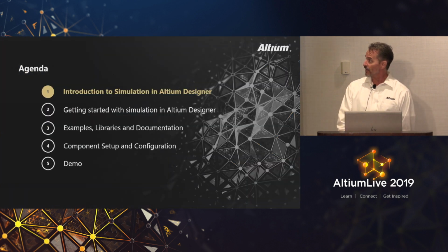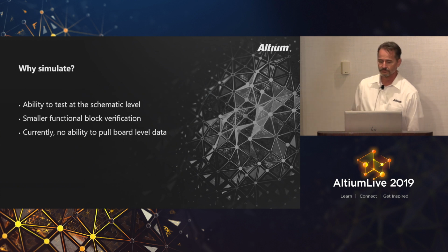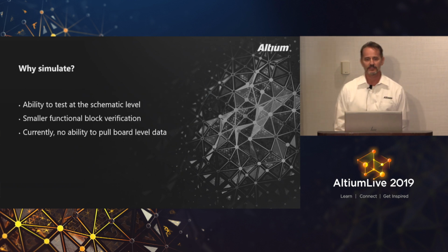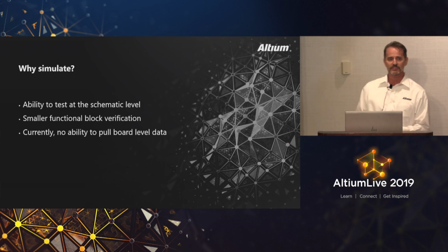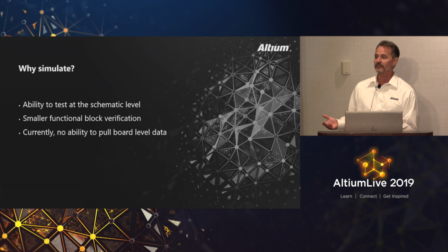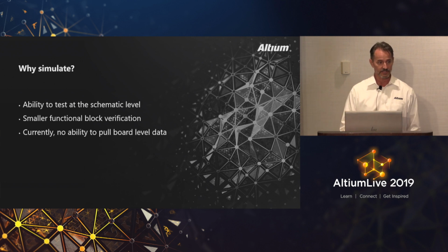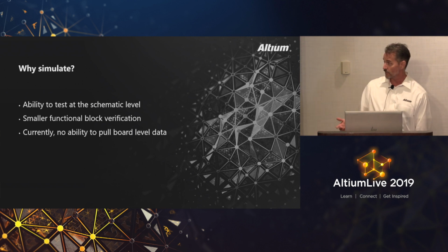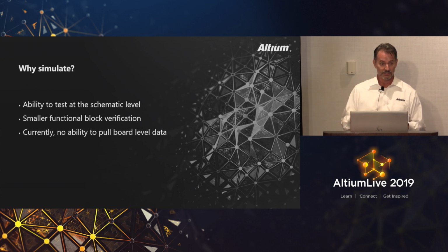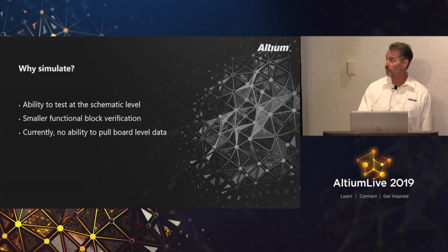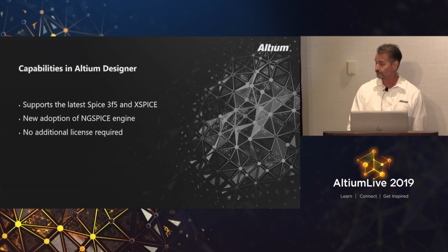So a quick introduction for our agenda. Of course, why simulate? It allows you to do some level of testing. You have your filters, you have some active responses on your design, and especially when you're prototyping, it's easier to decide on different changes and what to implement at the schematic level. It's a lot easier than making changes once you finally get the finished board. Although you may want to test on a proto board if you can, or you can get your preliminary values simulated at the schematic level.